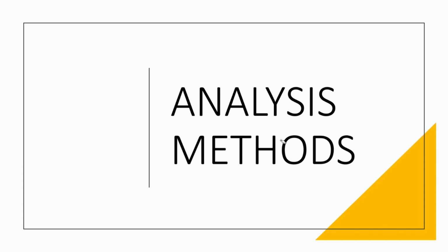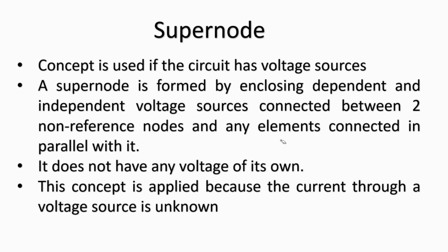So, today we are going to continue with another very interesting analysis method, which is called the concept of supernode. Now, this concept is used in circuits that have voltage sources, and these voltage sources could be connected between two non reference nodes or between a reference node and a non reference node.